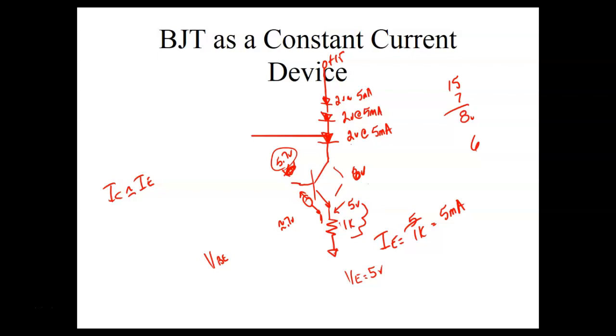And I've seen this used on car burglar alarms where you put LEDs that flash, and they say you can put up to 5 LEDs and you just hook them in series. Well, how can you do that? Well, they're on a constant current source, right? You understand? So what you do is you come up here and you set the current with your emitter resistor.